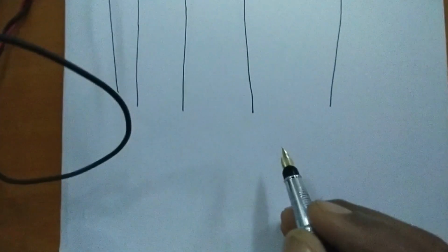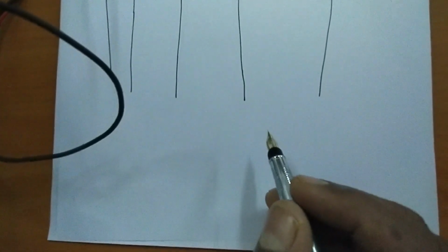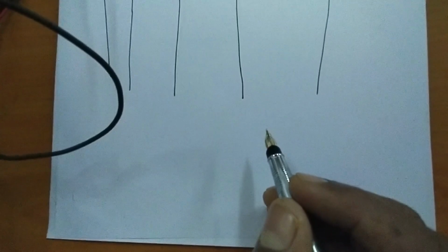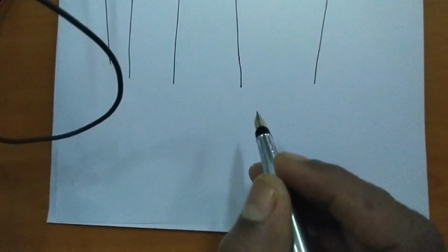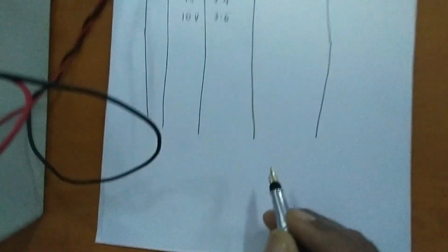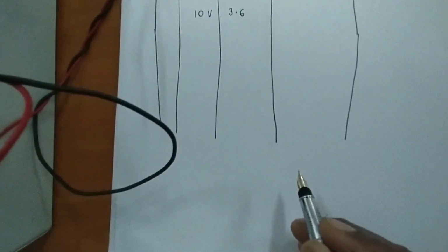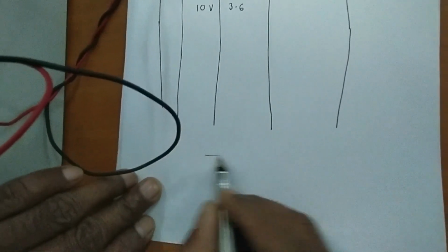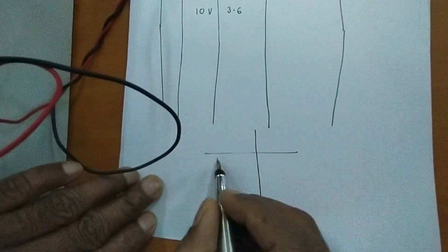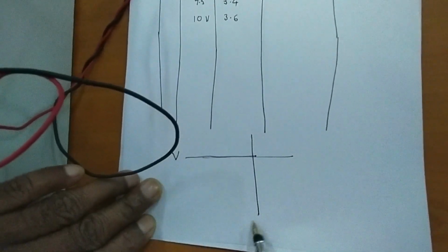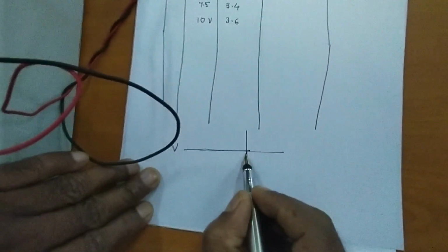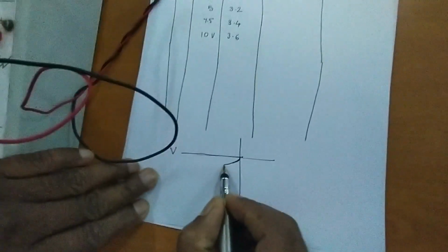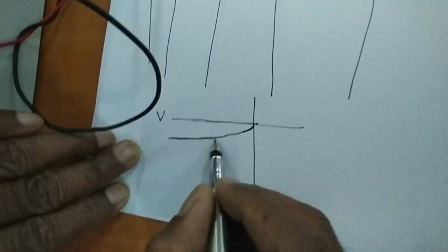Because if you draw a graph between the voltage and current, here the current in the photodetector passing through the circuit is a reverse current. Because we are operating this in reverse bias, the current through the diode is reverse saturation current. And hence you can plot a graph by taking voltage V here and current I in milliamperes. So it may start here and initially stay somewhat constant, then increase and then become constant like this.